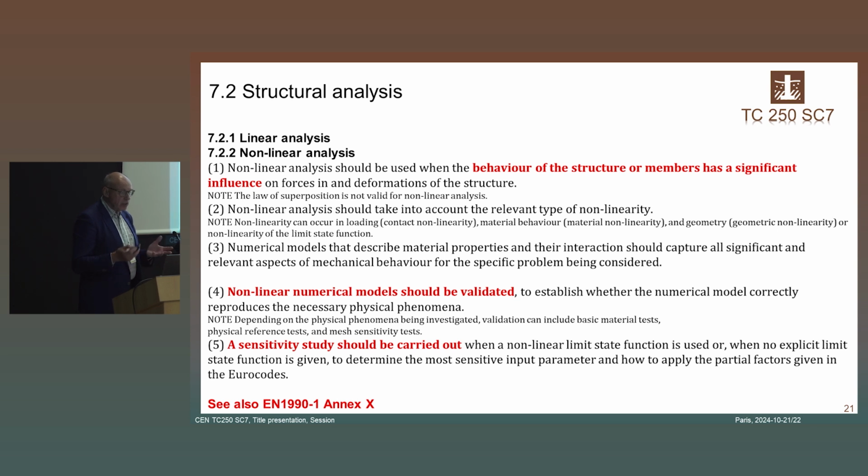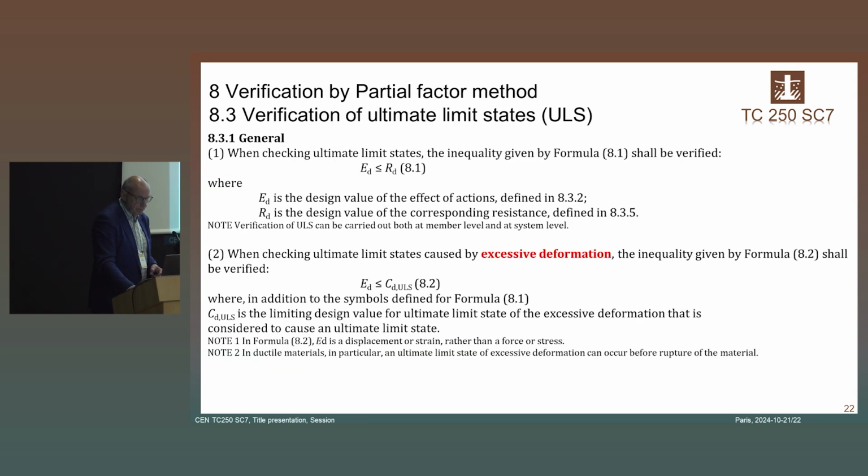Non-linear analysis should be used when the behavior has a significant influence on the forces, which is often in geotechnics. I think non-linear numerical methods should be validated. A sensitivity study should be carried out. I think those things are really logical, and we have taken that on in 1997.